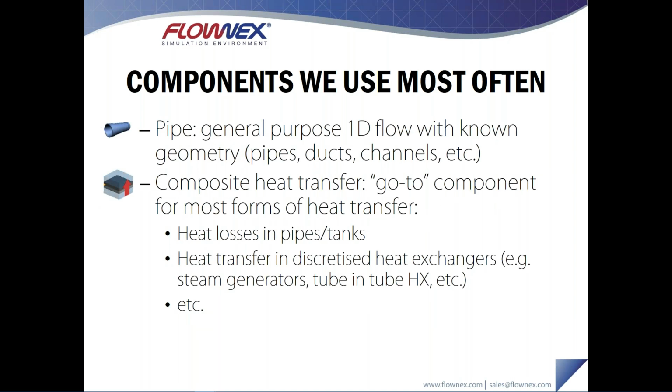Okay, these are more general components. When it comes to any 1D flow with a known geometry, so by known geometry, I mean a known diameter or a known flow area, something where we can actually calculate a velocity in the component. In that scenario, I'd suggest using the pipe component.